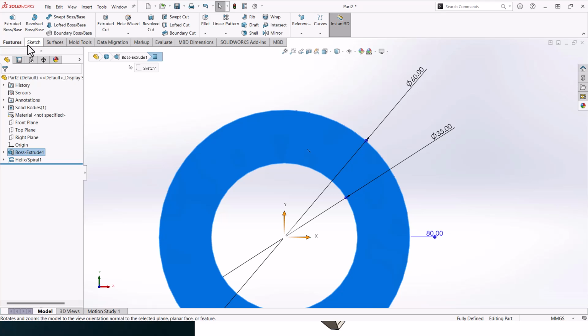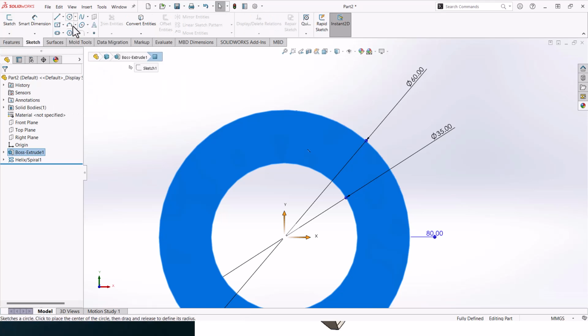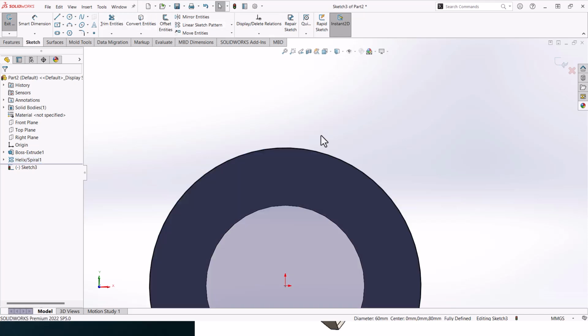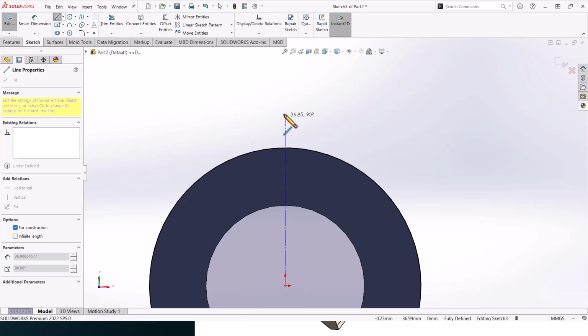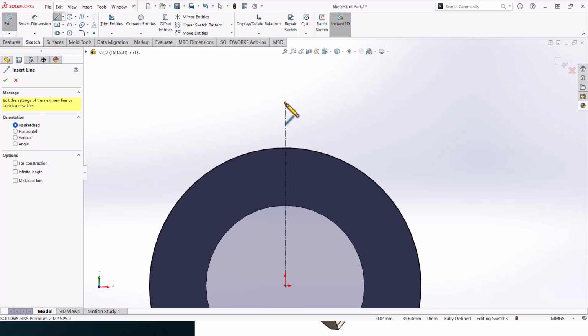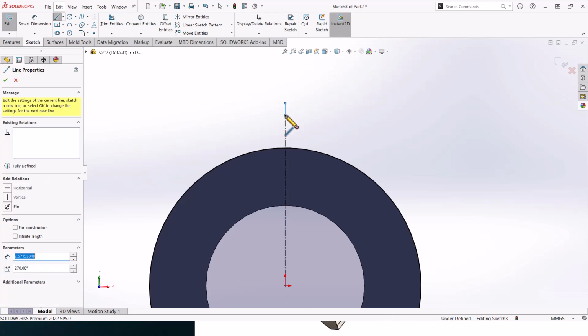and now let's create the cutting tooth of the cutter. Right, so click on the front face, click on Sketch, and then go to this edge again, click on it, convert entities, and create a center line starting from the middle point and then start drafting the cutting edge.